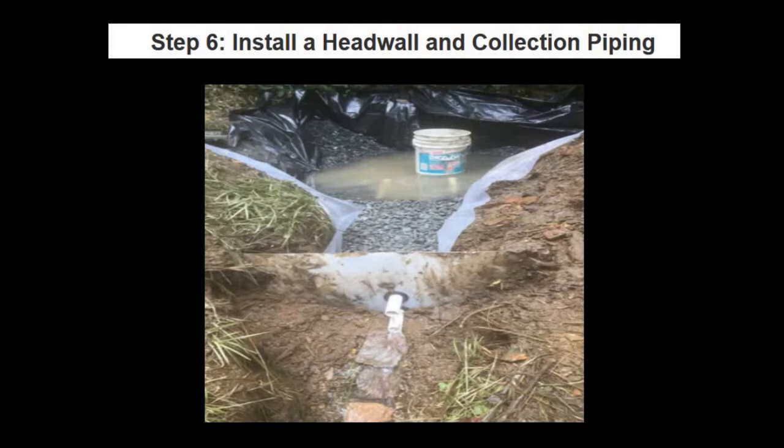And then they put rock, rinsed river run rock, drain rock it's sometimes called. They're round rocks that are rinsed, and they put that in so that the water has a place to go rather than a standing puddle of water. It's now interwoven in between the pebbles in the gravel. And then a dam is built at the end of it.